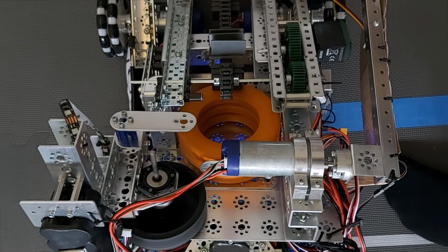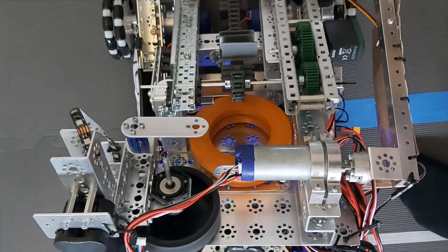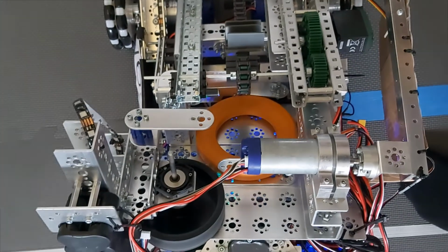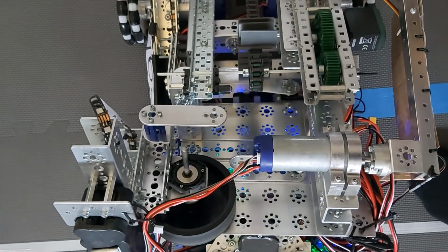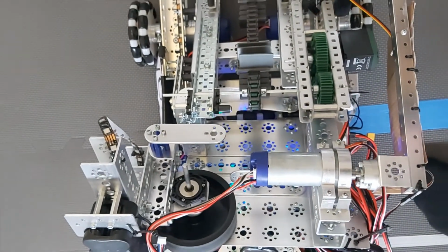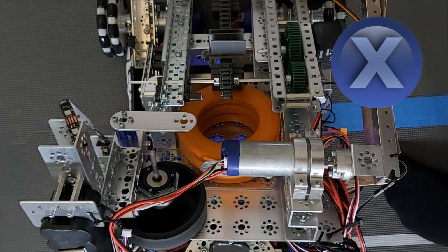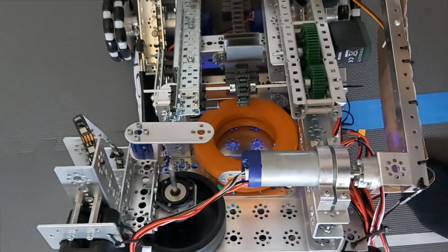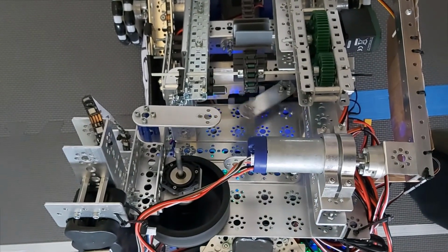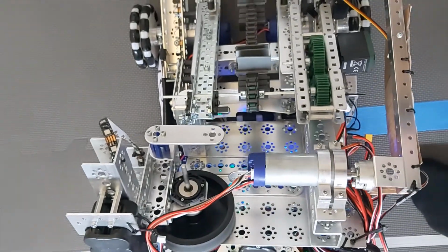We also have certain programming features which make controlling the robot in the teleop period easier. Shooting on our robot, for example, is actually a very involved process. First, the shooter needs to turn on and rev up to the correct speed. And then from there, the ring pusher must extend to push the ring into the shooter wheel, and then retract so that it lets the rings above it fall down and allows the cycle to repeat. This process is all abstracted away to a single button press that'll shoot all 3 rings.